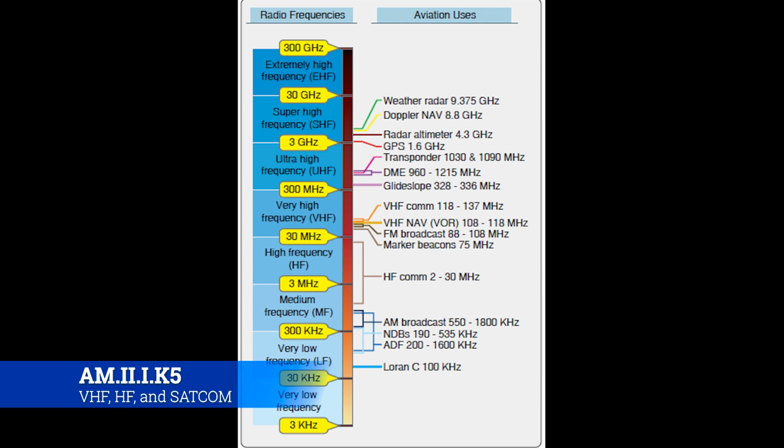But there are still a lot of places that do RNAV approaches, Texarkana being one of them. The glide slope is basically, and we'll get into this a little more in a subsequent class, it transmits a radio frequency that degrades and changes at different points. That way the airplane knows, hey, I'm below the glide slope, I'm above the glide slope, or I'm on the glide slope.